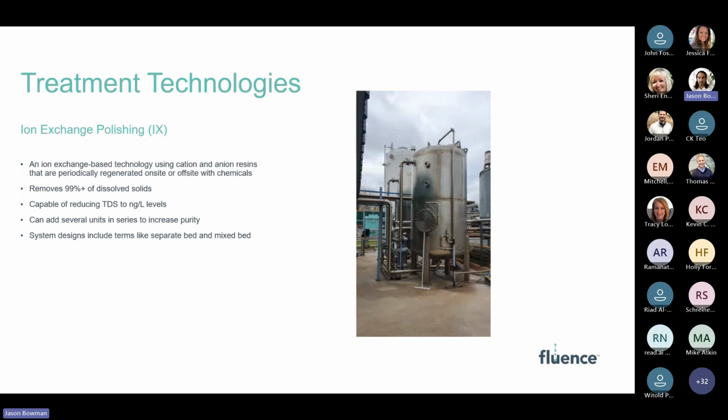One potential solution could be to utilize EDI or CEDI technology as a polishing stage just downstream of the RO. And then you can also utilize a mixed bed system to produce your final polished ultra pure water. Oftentimes, there are also third-party companies that can provide offsite regenerable mixed bed systems, which would also remove the need for hazardous chemicals to be on site as well.